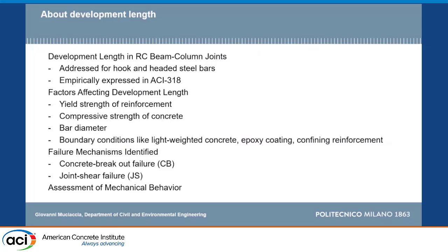In joints, there is this superimposition of a way we can see the joint, or the anchorage in the joint. So the anchorage in the joint is an anchorage of the bar. Is this anchorage to be defined as a bar with its development length? Is it an anchorage as we see, from the perspective of anchorage in concrete? Is it a joint shear failure? Is it all the same thing, or should we see them as different types? Okay, this was to look a little bit at that.